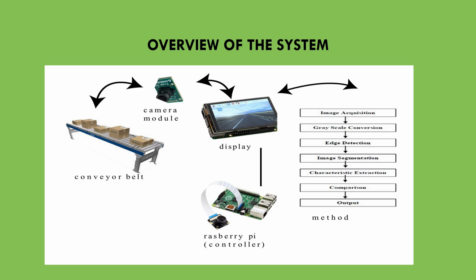A spherical optical transform and a defect preservation transform preserve any defect levels on objects even below the roller background and compensate for the non-Lambertian gradient reflectance on spherical objects at their curvatures and dimensions. Defect segments are then extracted from the resulting transformed images. The size, level, and pattern of the defect segments indicate the degree of defects in the object.